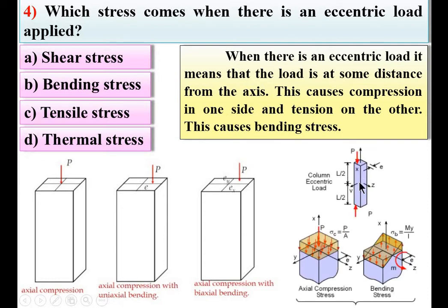If I apply the eccentric load, then on one side it will be compressive stress and on the other side tensile stress, and the combination of these two stresses is called bending stress. So B is the right answer.